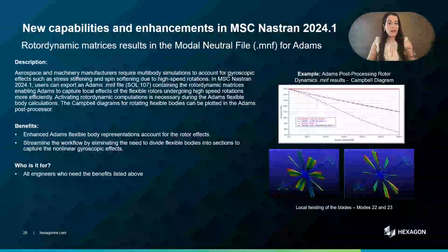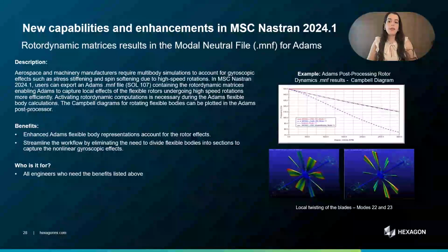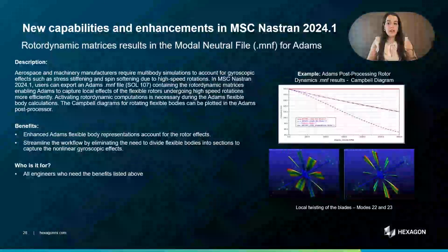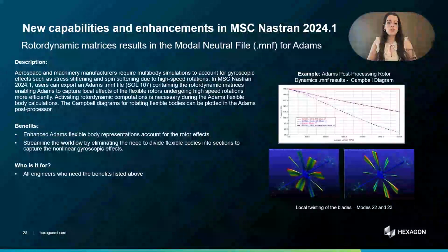Another modal neutral file or MNF enhancement includes the ability to have rotordynamic matrices results available in the MNF file for Adams. Aerospace and machinery manufacturers require multi-body simulations to account for gyroscopic effects such as stress stiffening and spin softening due